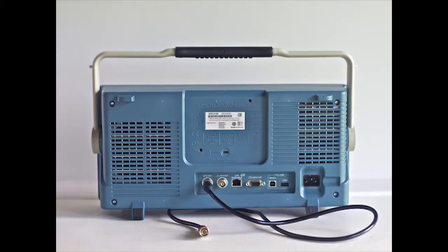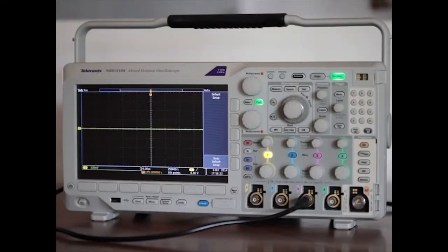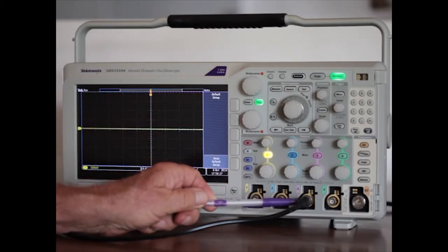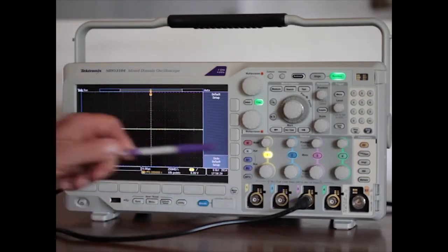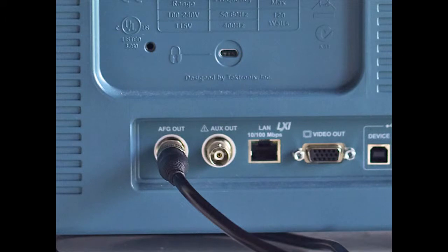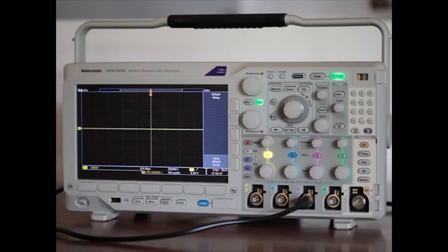Now it's quite easy to get this arbitrary function generator up and running. First, you connect a short BNC cable in back as shown. Then, in front, you connect it to one of the analog ports. A second socket in back, auxiliary out, allows a feed to another machine, or it allows the technician to connect to a circuit under investigation, and it provides an alternate triggering mode. A good idea is to make this BNC cable as short as possible.